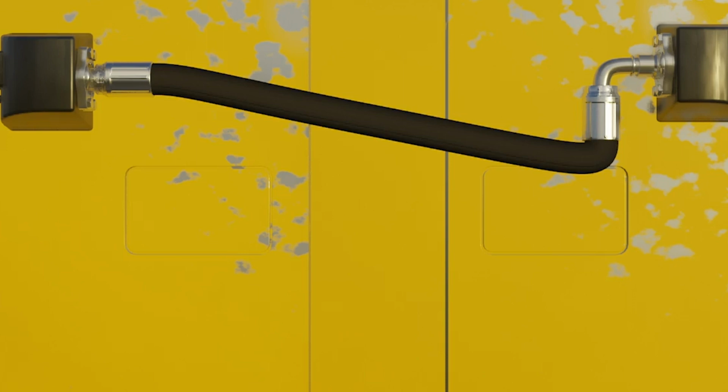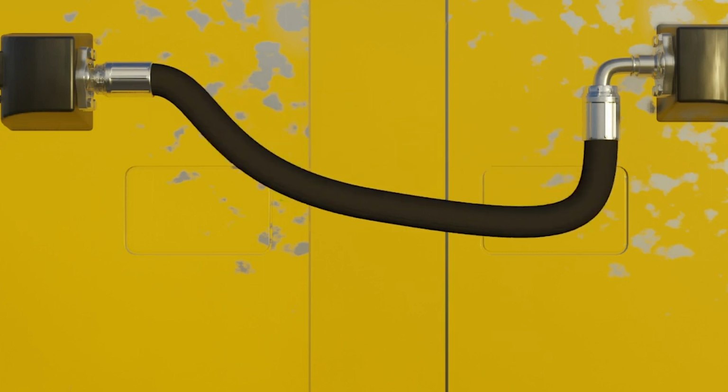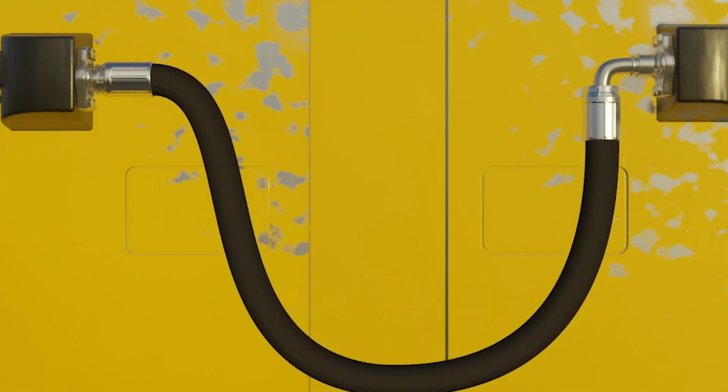Looking at the image, what do you think is the problem with this hose assembly, and what can you do to correct the problem? The hose length is too short. This is putting significant strain on the hose ends, and the bend radiuses in the hose are too small. The reinforcing layers will be adversely affected, allowing the medium to burst through the side of the hose. Replacing the hose with a longer hose would be best practice in this situation.